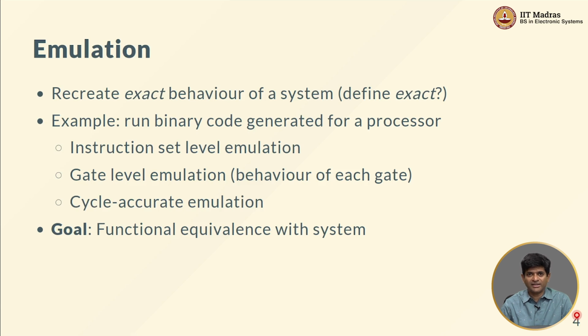Now, arguably, if you actually had the complete Verilog for a system, and you just run the Verilog simulation, in some sense that's also emulating the behavior of the system, right? However, when we talk about emulation, we usually talk at a slightly higher level of abstraction. I do not want to spend that much time doing a fully gate level accurate simulation of a CPU. Instead, I can abstract it out. Rather than considering all the individual flip-flops, AND gates, full adders and so on involved in incrementing the program counter, I can just write PC equal to PC plus 4 and go to the next address, right?